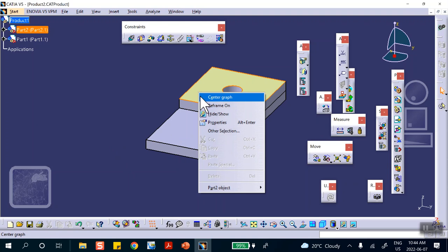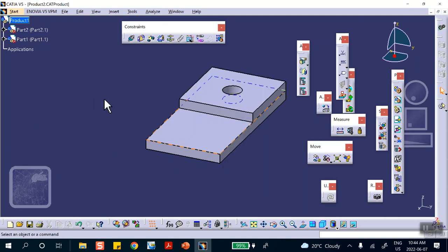This thing, because I projected it, a surface came with it, but I don't need it. I'm going to hide it. I can't delete it because I projected it. Remember, I projected that entire face. Good. No more bolt. If I save it, it's going to be fine. Product 1 is not product 1. It's a bad idea to leave this thing as the product 1 name. It's a good idea to change this thing. You get confused, because there is already a real product 1 there. But let's save this.